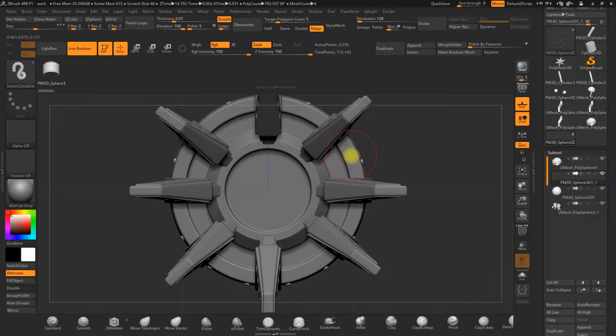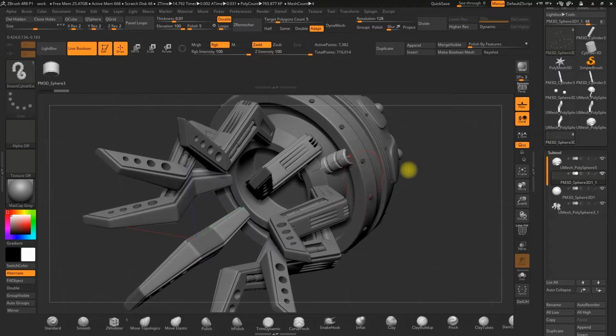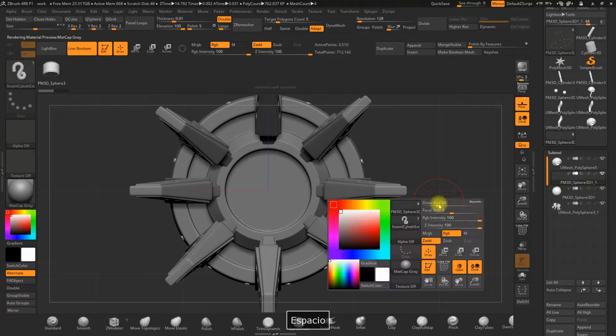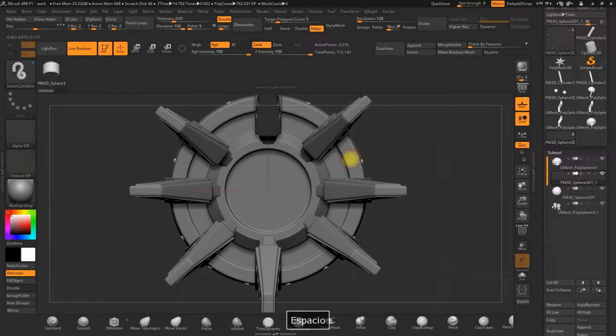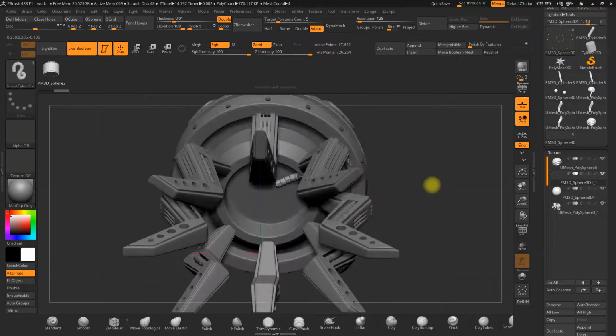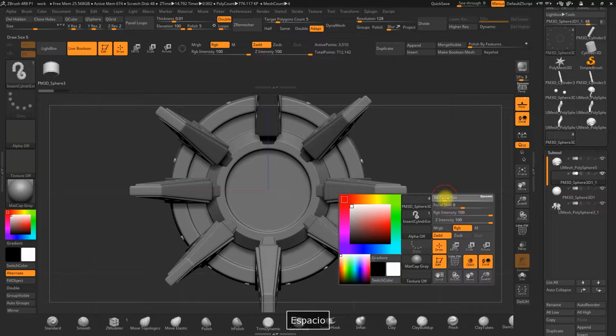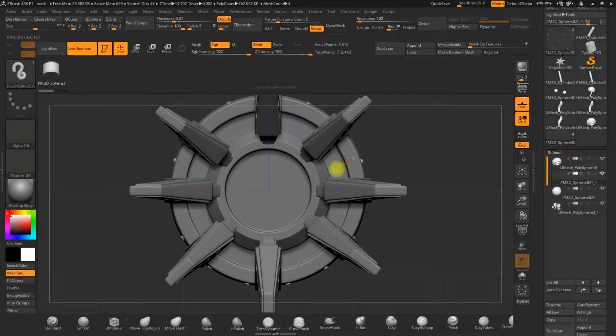For example, from here to the middle, move it, and it's like a tube. So depending on the diameter of the brush, the tube will be narrower or wider. In this case, we want a narrow tube, so we'll lower the diameter of the brush, and we'll repeat that same procedure. As you can see, now the tube is smaller. I think this is better.